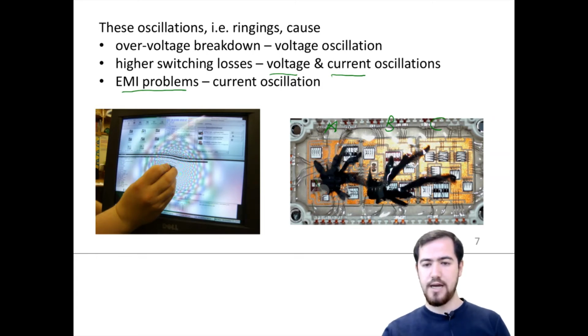You see here an explosion which caused a black powder around these switching components, and we have seen another problem on the right hand side at phase B. As you see, there is a gel inside these switching components, just to keep all components inside the package. When it explodes, it is actually provided by the manufacturer for safety.